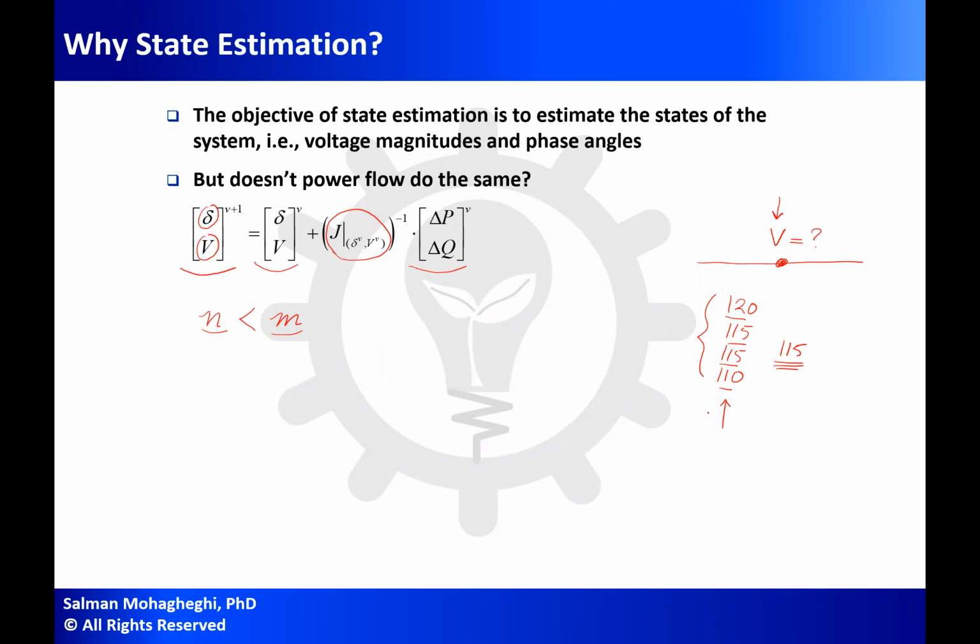What I'm doing in power system state estimation is exactly the same idea. I would include more equations than unknowns, and then I would try to find the set of V's and deltas that would fit those measurements statistically.